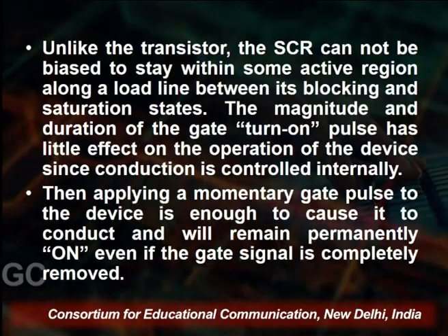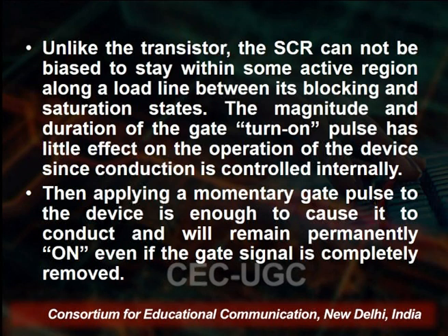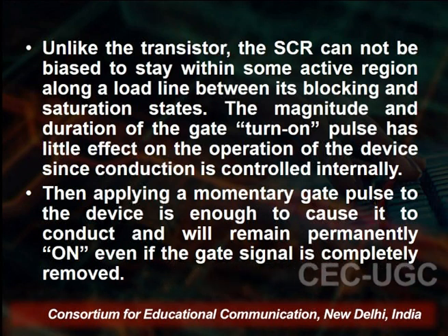So the application of any gate signal or pulses after regeneration is initiated will have no effect at all, because the thyristor is already conducting and is in the on state. Unlike the transistor, the SCR, silicon controlled rectifier, cannot be biased to stay within some active region along the load line between its blocking and saturation state.